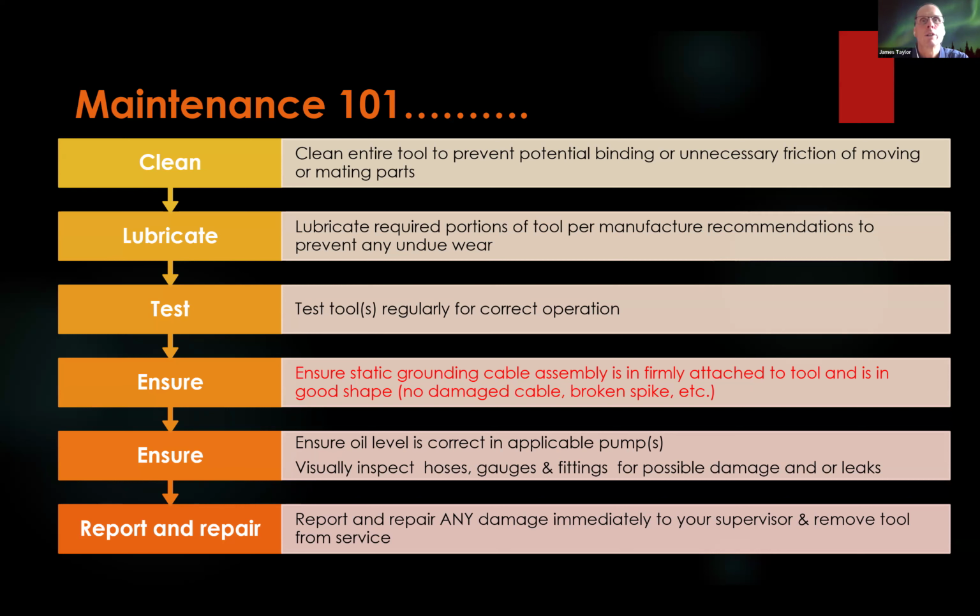Make sure your oil level in the hydraulic system is all topped up and it pumps. Visually inspect the hoses, gauges, and fittings for possible damage or leaks. Some of them can be high pressure oil. We don't want them to have an incident. And report and repair anything that's damaged. If you see damage during a job or after a job with the squeeze tool, report it and remove that unit from service. Again, it's very key that all those squeeze tools are looked after very well. Almost babied in one sense, that they're maintained that way, because when there's an emergency, they're going to work flawlessly.